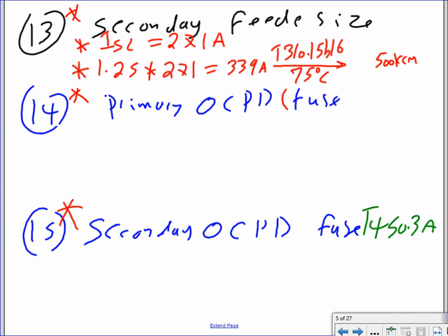The insulation that we're using, I'm going to assume it's going to be THHN, or indoor. I will ask you how many conductors do I need. Now, at least 3 conductors, right? Phase A, phase B. In a 3-phase system, you have to have at least 3 conductors. Now, the question would be, would I carry the same full neutral, or would I derate the neutral? We're not derating the neutral here, so if you don't know, carry full neutral.